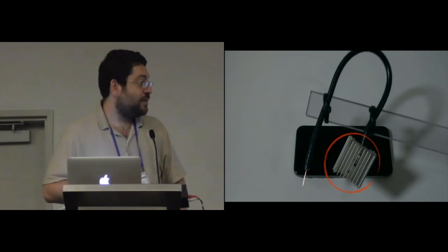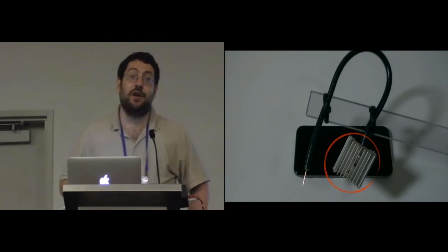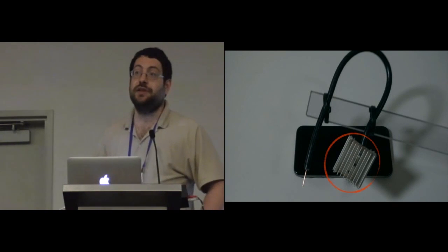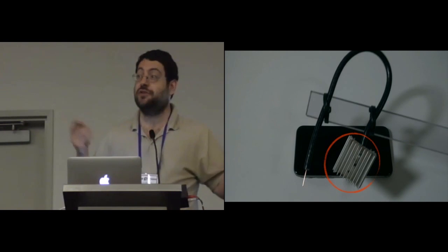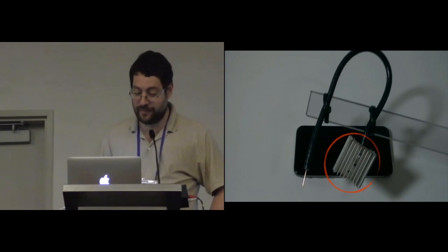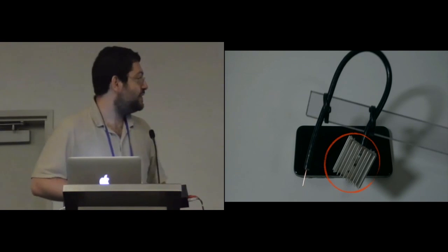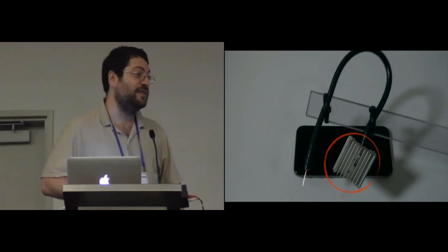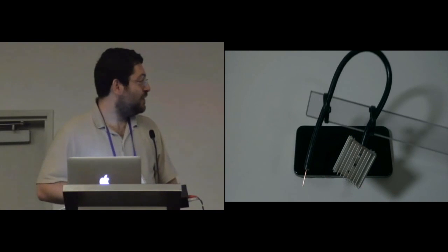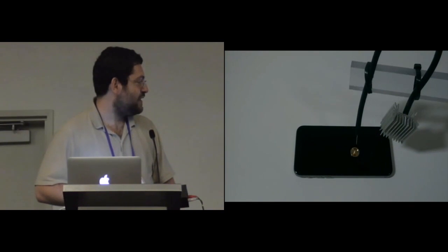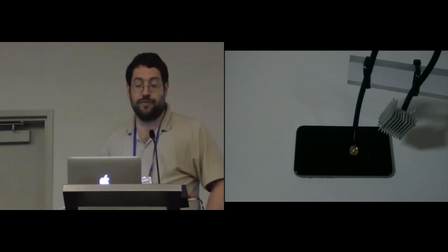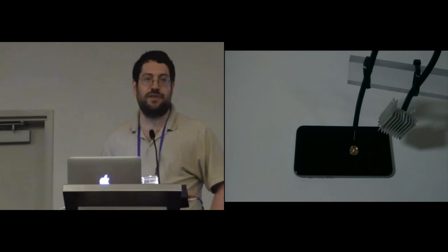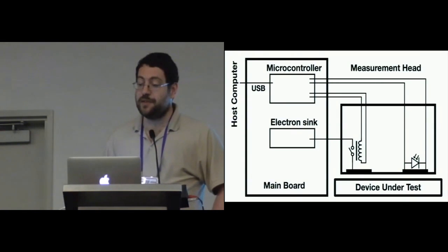And we've hooked that wire up to this, which is a heat sink. Now, we're not using it to dissipate thermal energy. We're using it as a bunch of conductive surface area, as a way to dissipate electrons out into the environmental ground. So I've connected this to an official scientific plastic poking stick, which is not conductive. And what I'm going to do is just tap it to the contact, and we see that that triggers a touch. So that's the basic idea of the hammer. All we need to do is replace the poking stick with a switch, and we have something that can actuate the touch.